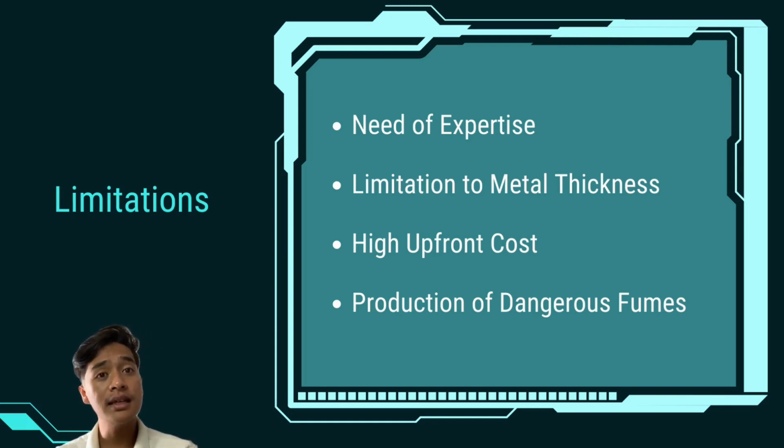The capacity of laser cutting to cut a variety of materials is one of its benefits. The thermal cutting technique simultaneously causes material to melt, producing harmful fumes and releasing gas. When cutting plastic, this rings particularly true. As a result, a robust ventilation system, which is frequently expensive, is necessary for a safe workplace.